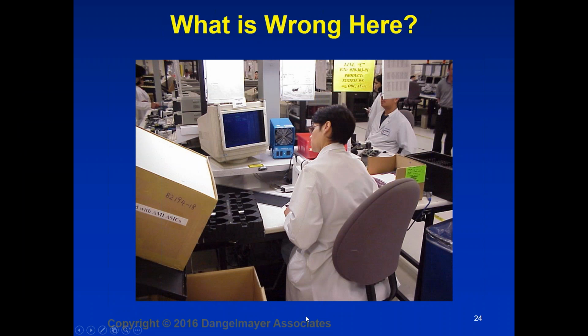Can we see what's wrong here? Do we see where the product is? And what we see here is that blue ionizer on the work surface has been turned into what we call a PCD. That is a personal cooling device. We find this phenomenon increases during the summer months when it might be a little warmer in the work area.